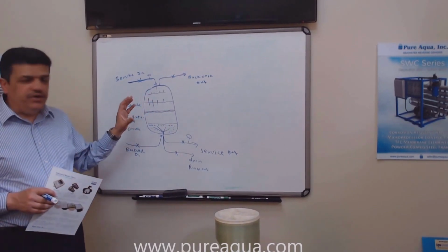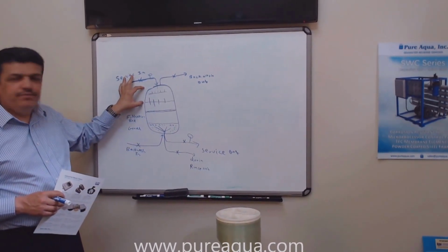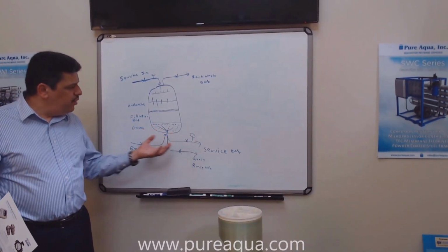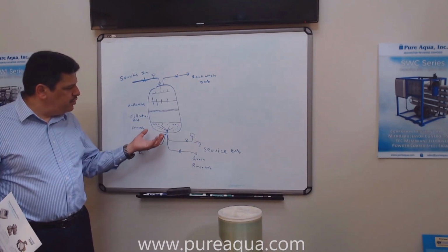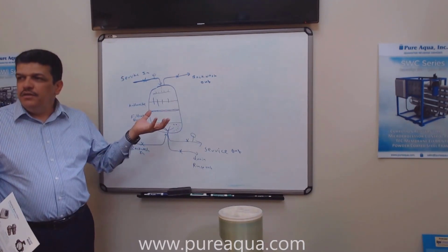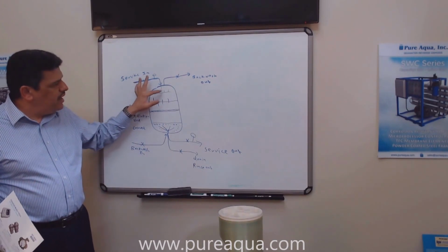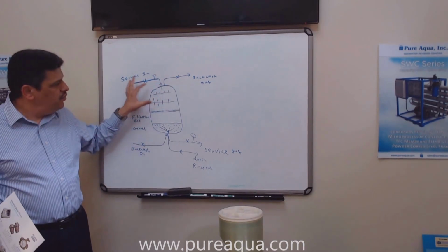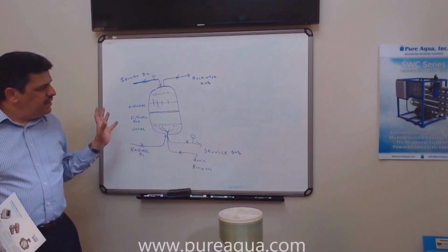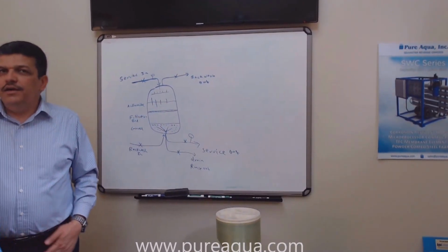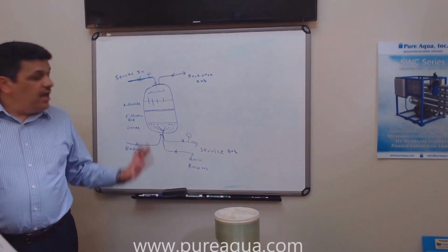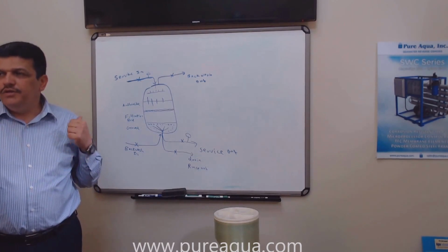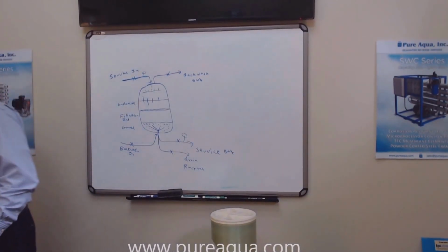When we design the media filtration process, we always leave about 35% free space here. Why? We consider that the water, when it's going inside for the backwash, is going to lift up the media. So we don't want the media to start going out of the drain from the top manifold. That's what we call the expansion space, or the freeboard. So that's a quick explanation about the media filters, and that applies to all the different medias, whether it's carbon, whether it's green sand, or whether it's AG, or any different media.